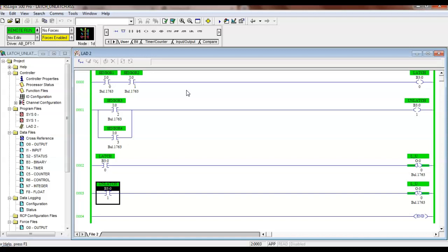Those are actually outputs. Those are true. They start with those. So look, you can look at my PLC. See that light on right there? So that means that output's latched. I'm gonna come over here and flip switch 2, and it's unlatched, so the light goes off. Up here, I got to turn this one and this one to make decisions. And now we latch. But as soon as I do that, I can make rung 0 and rung 1 both false. But the output is still on because it's what?